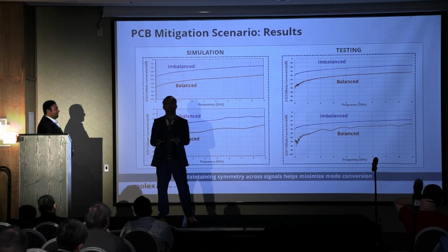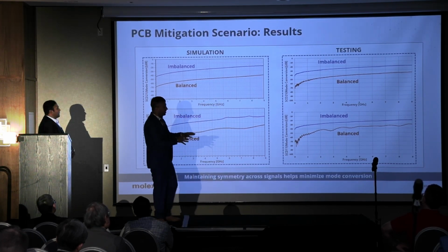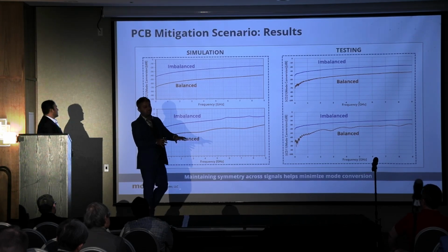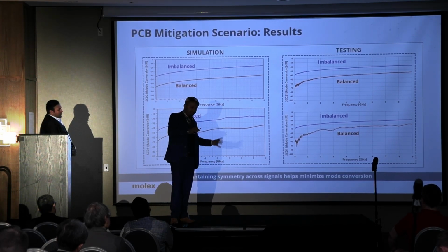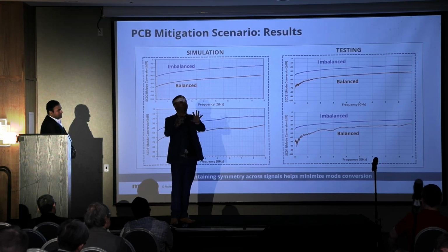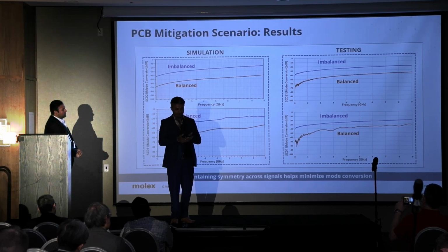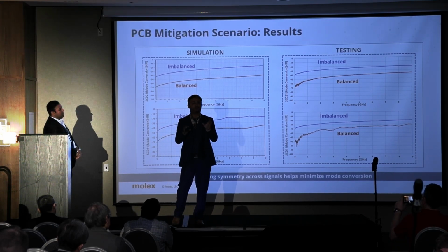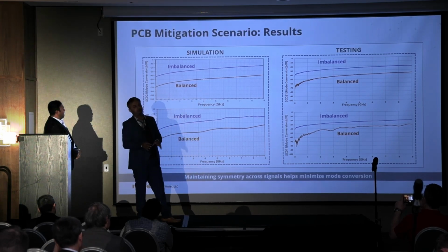But normally in a single pair Ethernet or in a unique kind of application, there won't be only PCB, right? There will be PCB, there will be connectors. Signal will be flowing in a PCB in TEM mode, it goes to the VIA, goes to the cavity mode, again it sees a different structure, connector, again sees a different structure, cable. So a lot of changes happen in the propagation, right? Different electromagnetic field radiation. So always we have to look from a system level perspective, right?